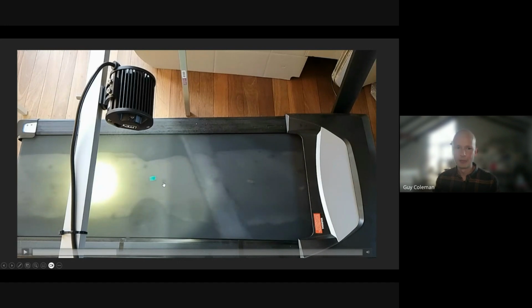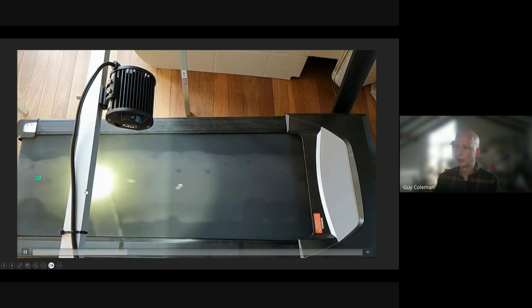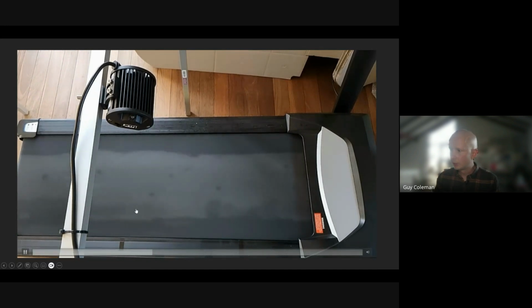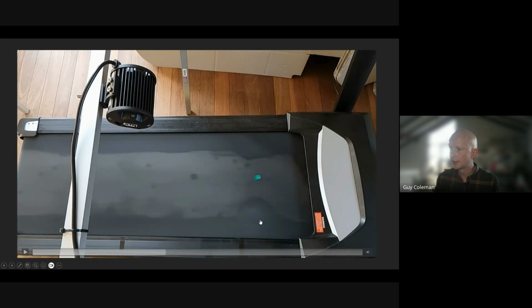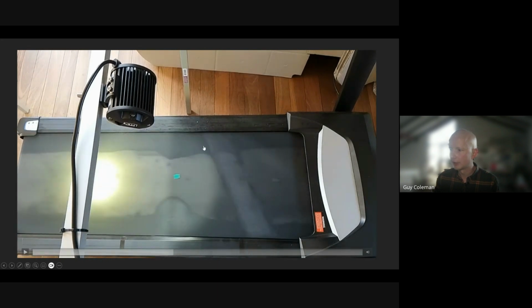And also making that a little bit modular. So say you put in the angle that you're angling your OpenWeedLocator at, and then it'll make sure that the right solenoids turn on when they should. That's just the slow motion of what we just saw. What's interesting to see is that these black lines here are the effective actuation zones for the owl. You see the weed enters the owl, and only once it reaches this point does the light start turning on. And that's just the processing time required to analyze every frame and then turn that relay on.